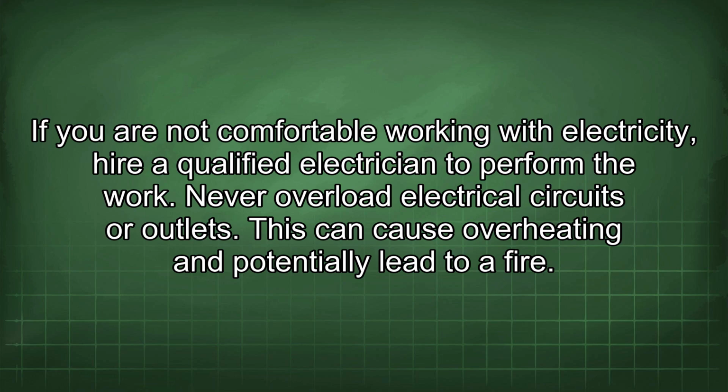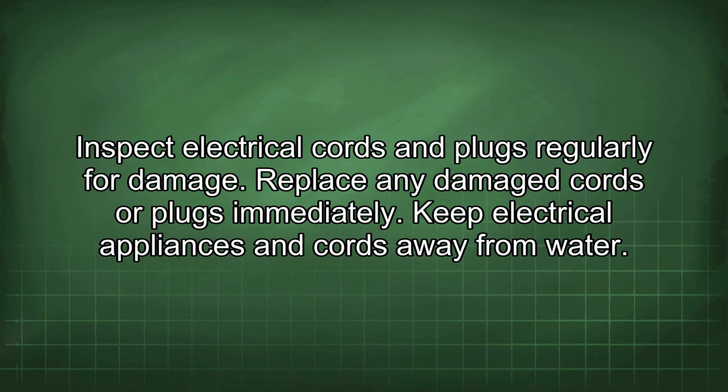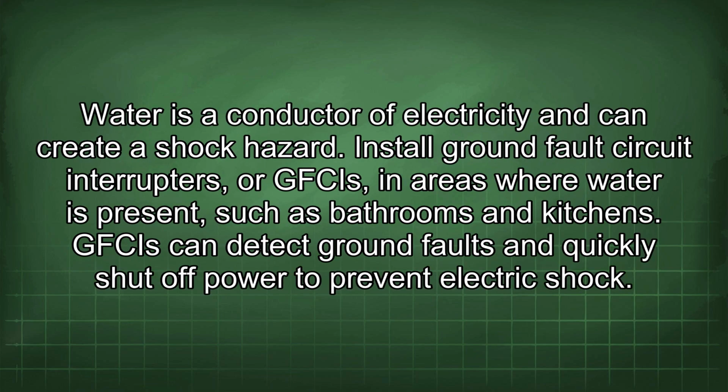Never overload electrical circuits or outlets. This can cause overheating and potentially lead to a fire. Inspect electrical cords and plugs regularly for damage. Replace any damaged cords or plugs immediately. Keep electrical appliances and cords away from water. Water is a conductor of electricity and can create a shock hazard.